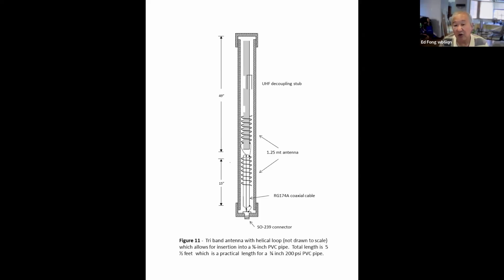You guys probably noticed this on VHF, UHF. Boy, you change coax and the resonance goes off, easily, 0.5 to 1%. And the problem is if it goes off 0.5 or 1% because you change coax, well, 1% at 450 megahertz is 4.5 megahertz. It's a lot. So I recommend that you always tune the antenna.